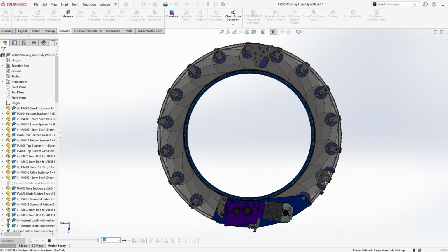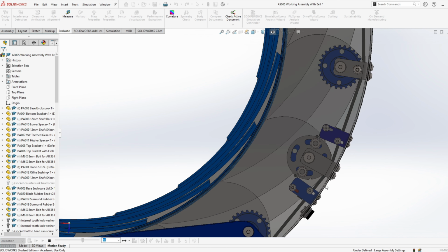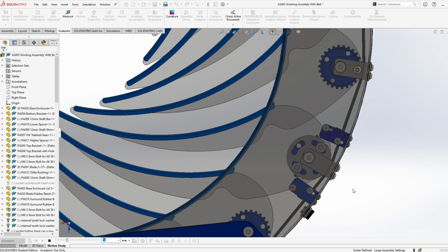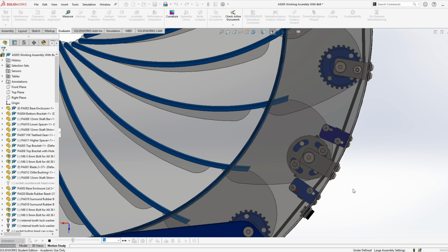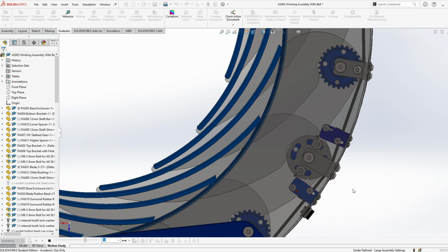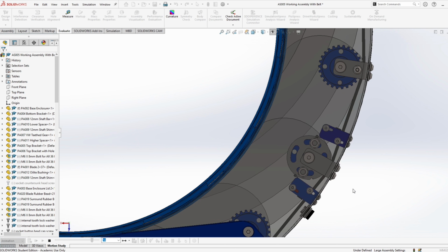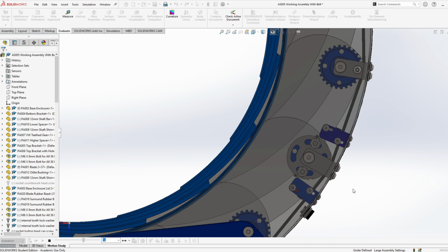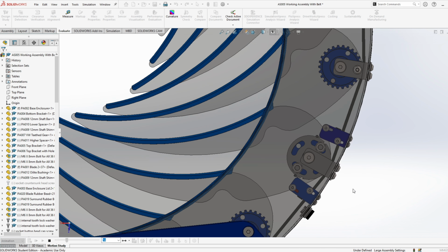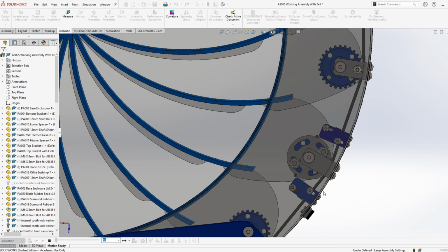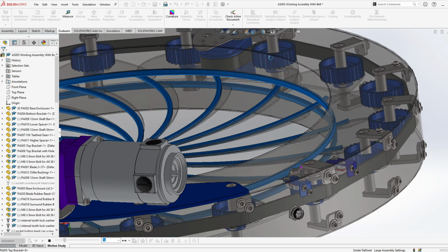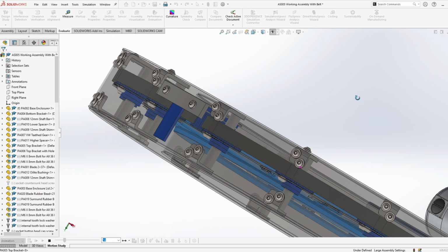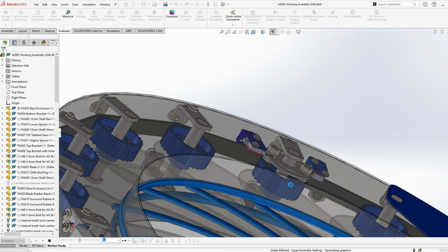So I'll zoom in here. This bracket was adopted to act as a limit switch detector plate for prototype 2, which is used to determine what state the Aperture is in, open or closed. It is fixed to one of the gears using two M8 threaded studs. So I'll get a wee side view of this here. So you can see the two studs here.